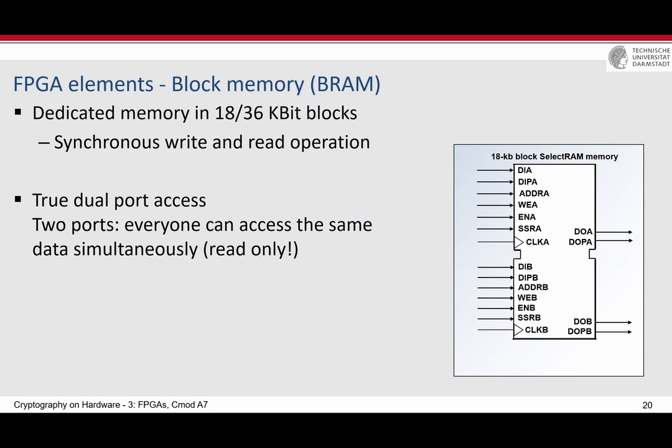It's like a lookup table, but of course it's actually a lookup table. The big difference between the block RAM and the LUT is that the block RAM is larger, but at the same time, you need a clock for block RAM. The lookup table doesn't have any clock. It's fully combinational. But block RAM has a clock, which means it reads from the memory. You give the address, and given a positive edge of the clock, it reads the value from the memory and puts it in the output register.